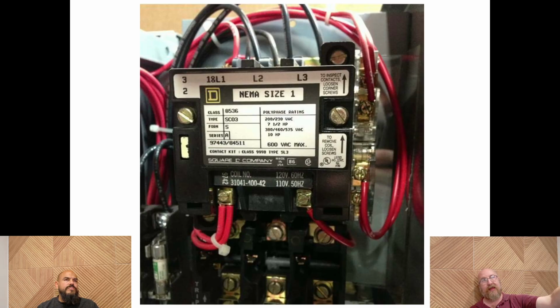And then on the bottom of that, you'll have T1 to L1 of a third component. Because you stack them up, you would never connect L1 to L1 on another component. L is a designator of a direction. It is not a designation of a terminal that we hook up to something like it. That's an important distinction to maintain.